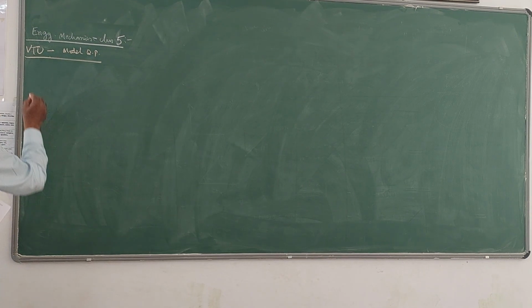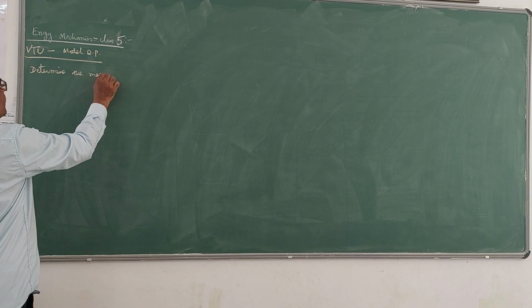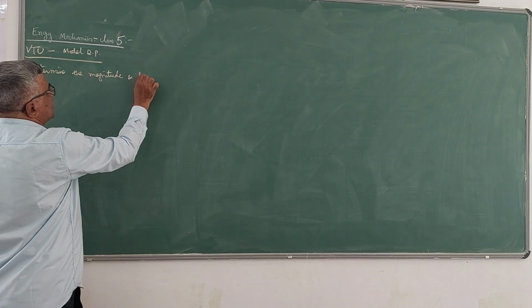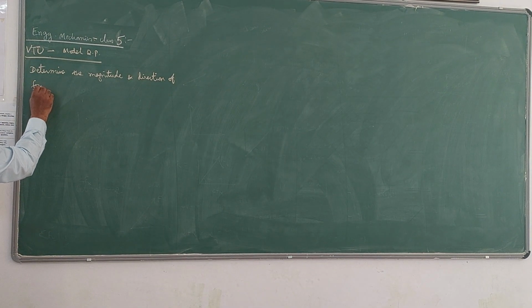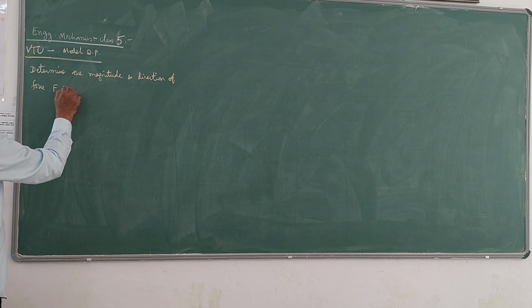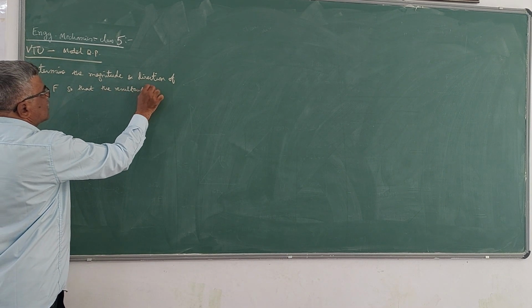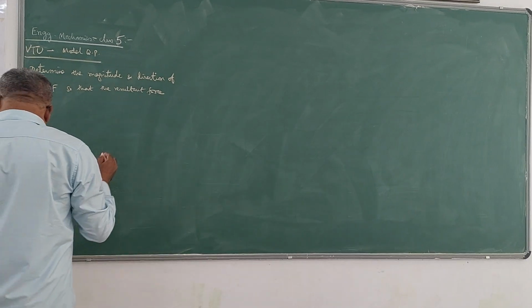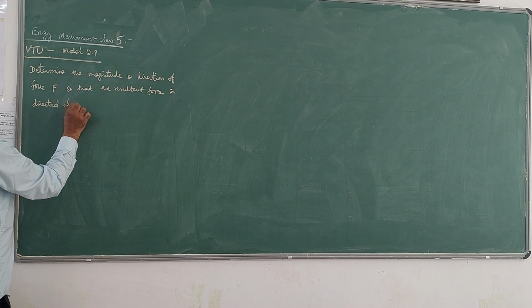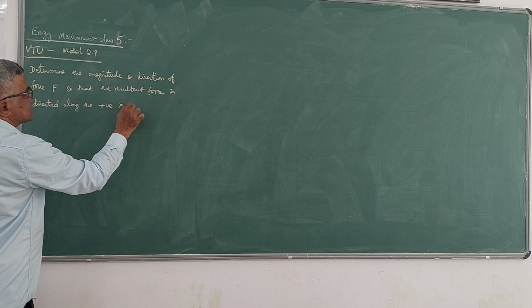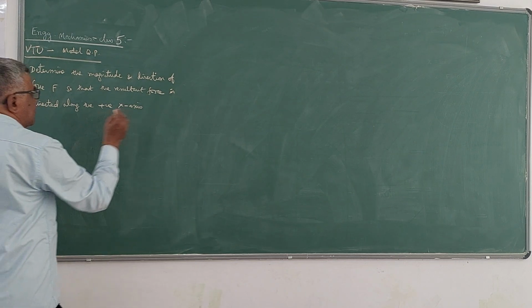Determine the magnitude and direction of force F, so that the resultant force is directed along the positive x-axis and has a magnitude of 1250 Newton.